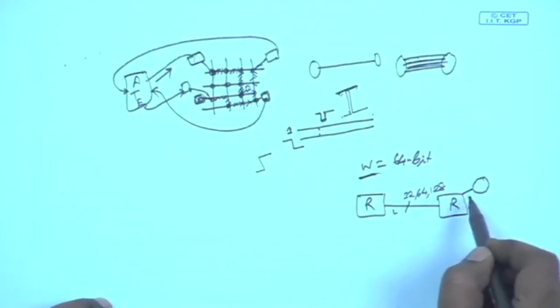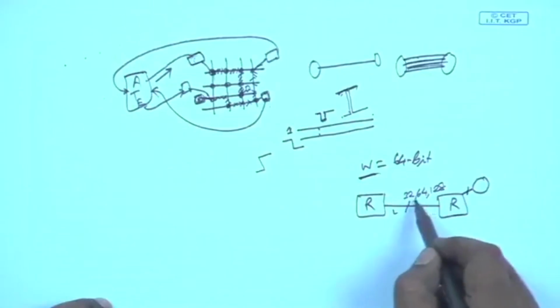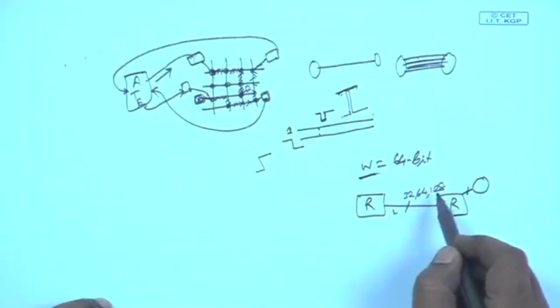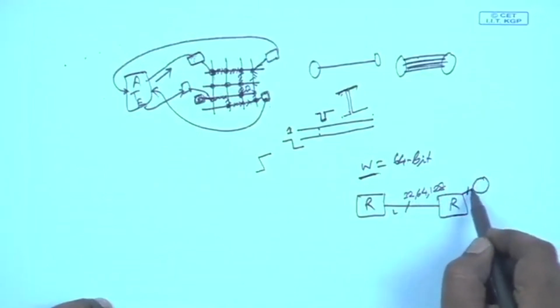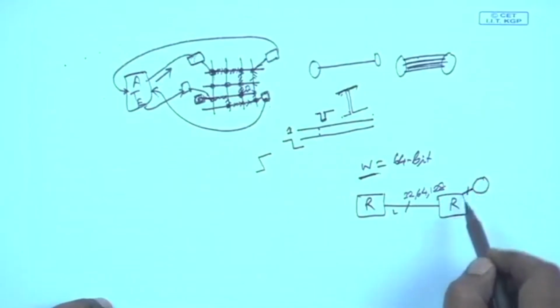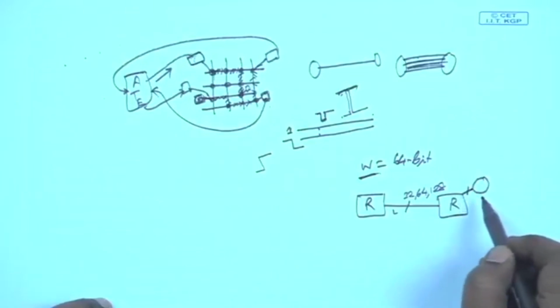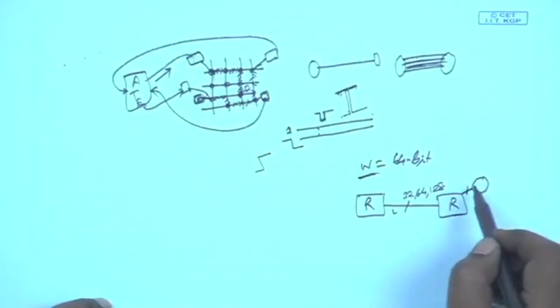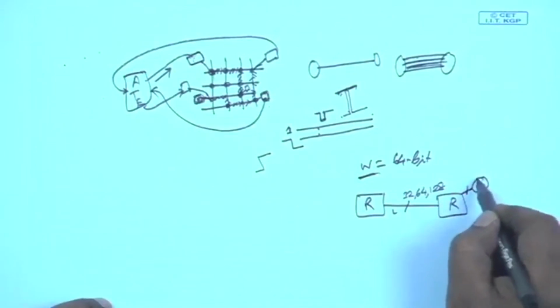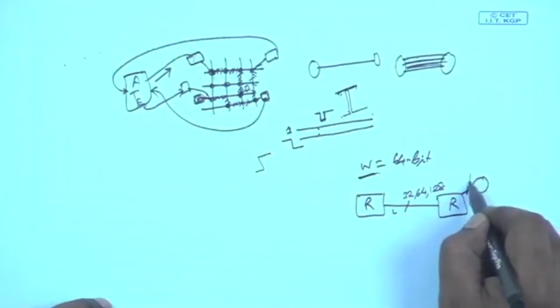So, this core, this local channel that is there, that is also of size 32, 64 or 128. So, this core gets 32 bit input, 64 bit input or 128 bit input, the other options do not exist. So, that has to be taken care of by means of this wrapper design that we have here.